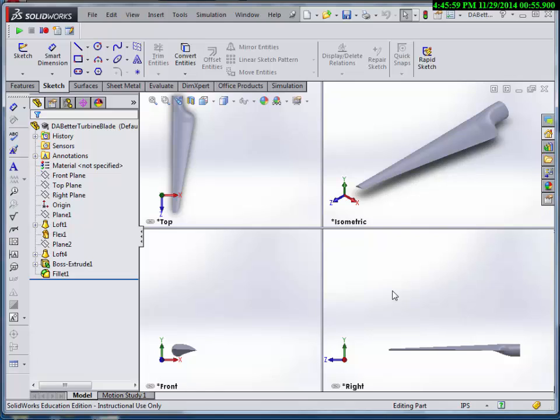What we're after, and here's an example of one in SolidWorks, is a shape that looks something like this. And if you notice, the front view is looking at the small end, looking down the blade. The reason for that is I would like to print some of these. In fact, you may hear some sound in the background right now, a 3D printer with the stepper motors making that sound, printing this particular blade in 2 pieces. In order for that to work as well as possible, what you want to do is start with the front view being the cross section.